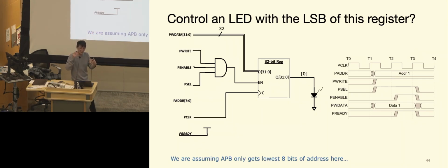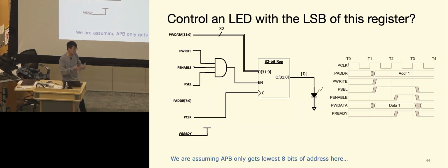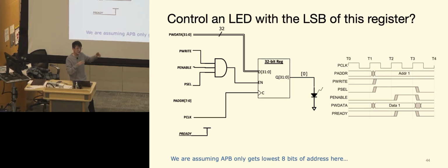Whenever there's a signal coming in, we just update it as the signal is ready. It's slightly different from before, but that's also pretty common inside a lot of peripherals. P-ready basically tells us this peripheral, this slave, is ready to do the operation that's needed. It's not the trigger, it's one of the triggers. It has to be able to do the instructions, but it's not the only trigger. You also need select and also enable from a higher level.